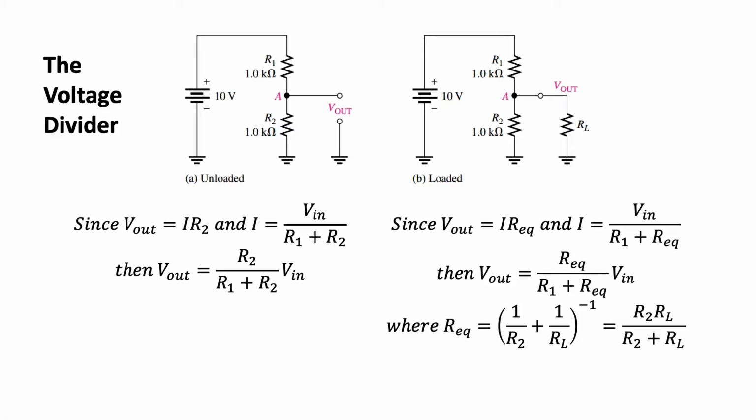In the non-ideal case, if RL is equal to 0.1 R2, then Vout is equal to 0.83 volts. The current through R2 is 0.83 amperes and through RL is 8.3 amperes. The current through R2 is smaller than the ideal 5 amperes, while the current through RL is larger, and the output voltage is smaller. This is called voltage loading. The output voltage changes because of the presence of a load resistance. The load resistance pulls on some of the current and reduces the effective voltage.